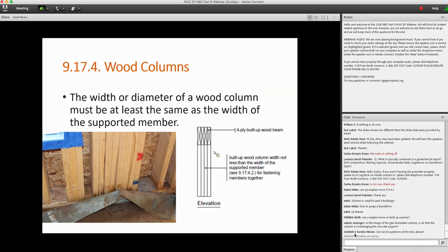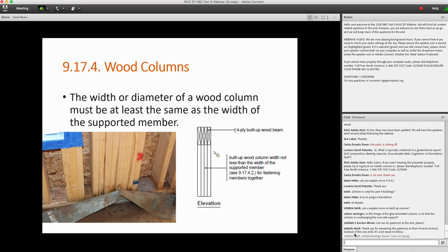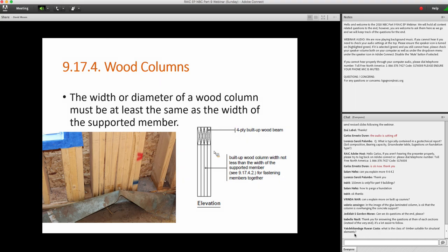Most carpenters, when they're trained, learn how to nail them together. There is an option as well to bolt them together. Under the Wood Engineering Design Code, CSA O86, capacities are given, and they're different depending on whether they're nailed or bolted together. But it's a very efficient way of using sawn lumber and individual 2x material. Now, when studs are built up within a wall, the load capacity is different than if it's considered an isolated post in the middle of a space.